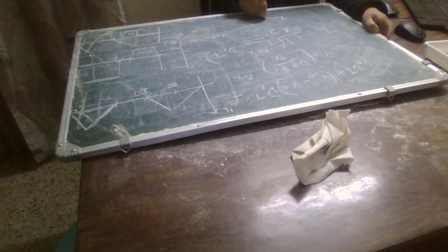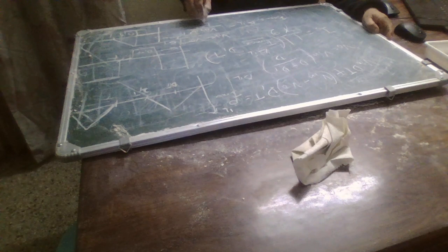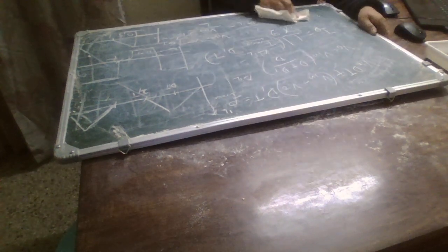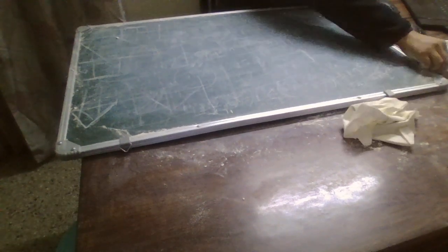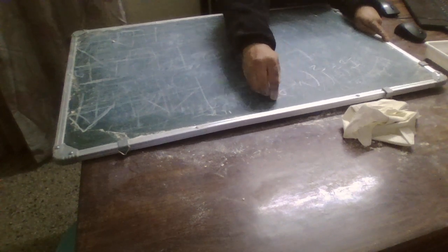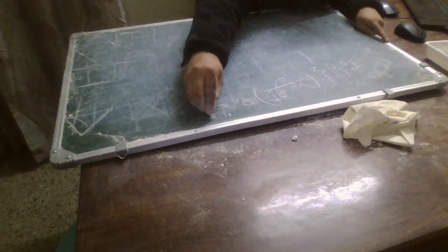Imax therefore would be delta IL, and we have already calculated delta IL was V input dt upon L. We can substitute the value of this into this expression, and we will get ID equal to half of V input dt upon L into d1, equal to V naught upon R.